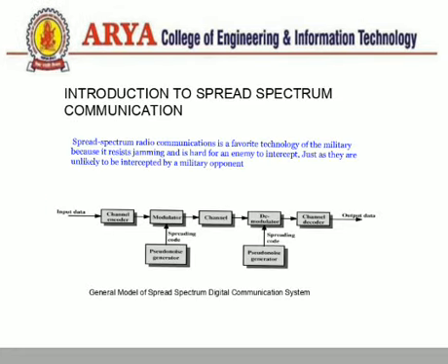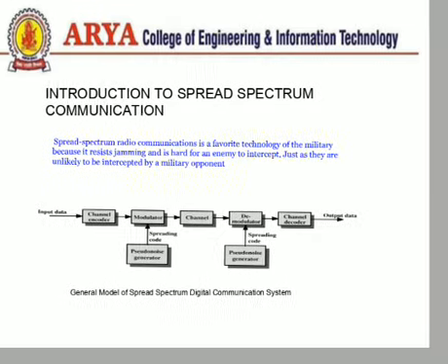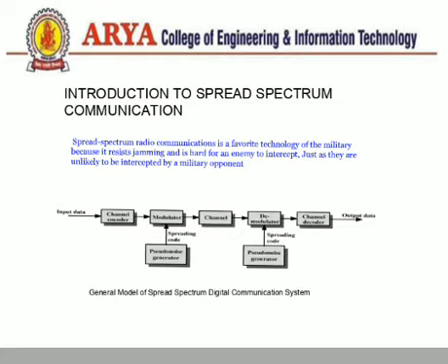First, introduction to spread spectrum modulation. Spread spectrum technology was initially developed for the military and intelligence communities to overcome the two shortcomings: interception and jamming. The basic idea was to expand each user signal to occupy a much broader spectrum than necessary. An important aspect of spread spectrum modulation is that it can provide protection against externally generated interfering signals with finite power. Spread spectrum techniques involve spreading the signal bandwidth B over the complete available bandwidth B total.